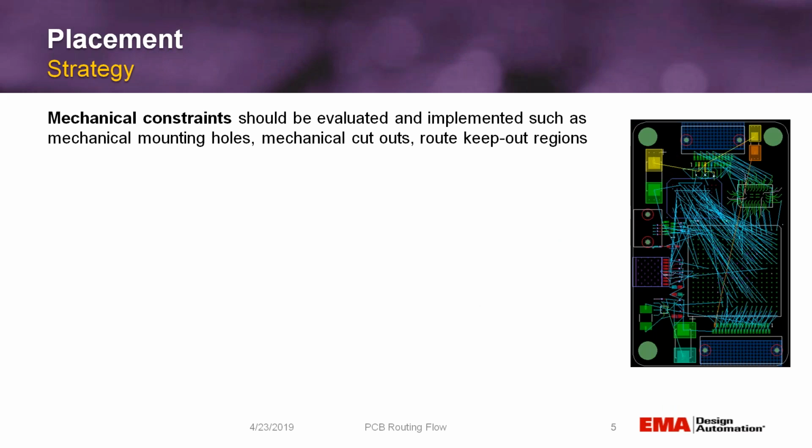So in the placement strategy, mechanical constraints should be evaluated and implemented. So you would want all your mounting holes established, any mechanical cutouts, keep out regions, all of those things would be defined and looked at in the very beginning.